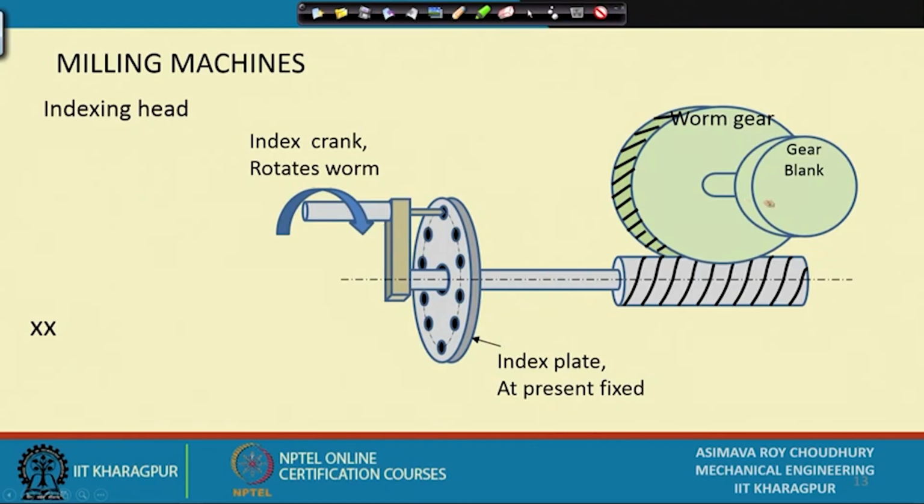Suppose I do not have the number which is required. What is that? So, let us take the case of a gear. In gears this is quite possible. I take up the problem of machining a gear, so let me write gear blank, 1 rotation, 40 rotations on the crank. So, previously I think you have already noticed, if this goes round, this shaft goes round and the worm goes round and the job rotates 1/40.